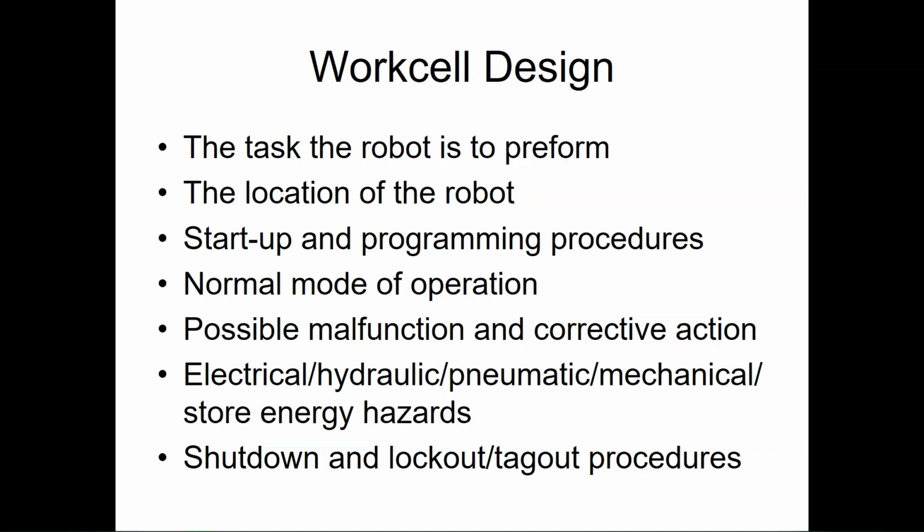But anything stored under pressure tends to have its own hazards, yeah? Namely the fact that if you're really not careful with some of it, it can inject that stuff under your skin and make you really ill. So that's something to always be aware of, is what kind of stored power it might have and how do I need to vent out that power so that I don't end up hurt.